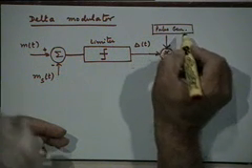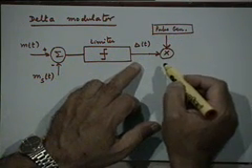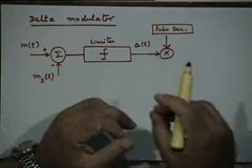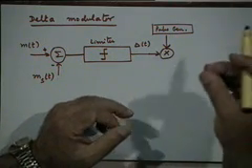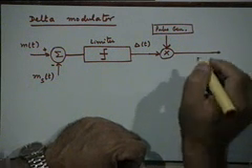So this is your carrier. In this sense there is a PAM going on here, pulse amplitude modulation, but the pulse amplitude modulation will lead to pulses which are either positive pulses of fixed amplitude or negative pulses of fixed amplitude, positive impulses or negative impulses of fixed strength. Is that okay? And that's your delta modulator output.